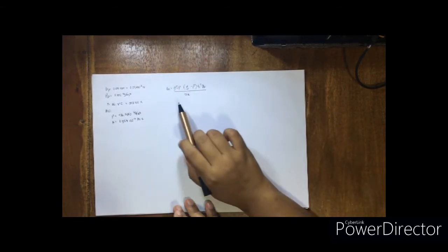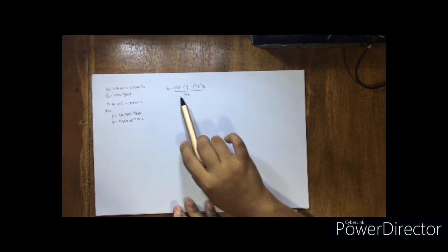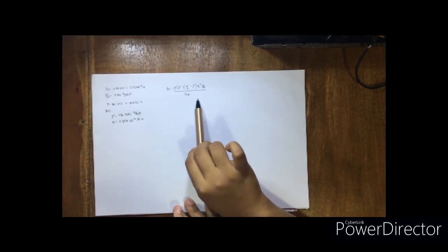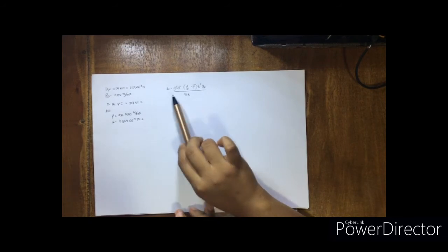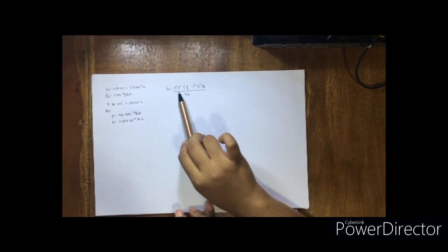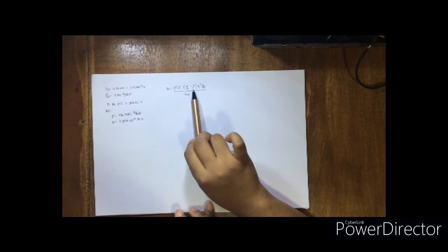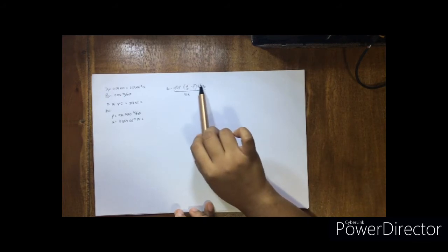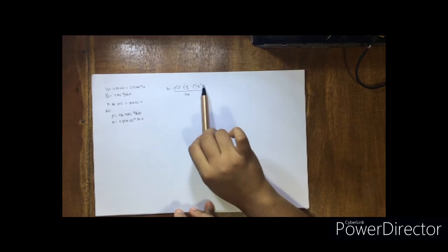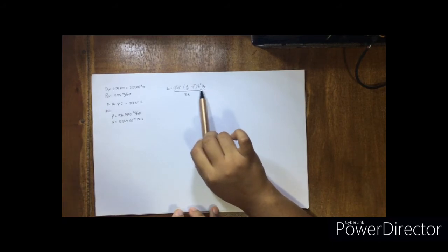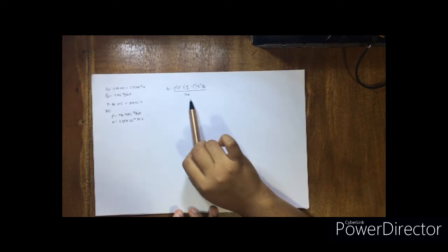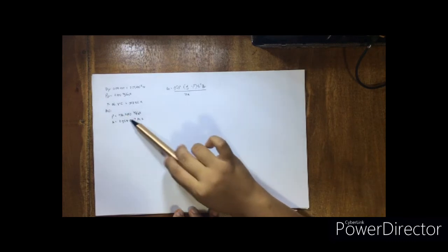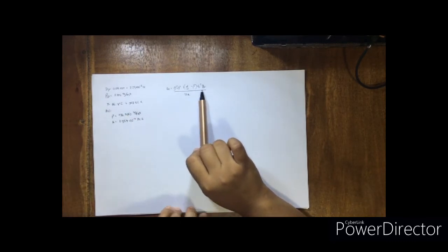So let's check if we have the following parameters needed in our equation for hindered settling velocity. So the gravity, the particle diameter, the density of our particle, the density of our fluid. We have the void, so we don't have the value for the void yet. And then we have this empirical correction factor divided by 18 times the viscosity. So before putting all the values, let's get first the value of the voids.